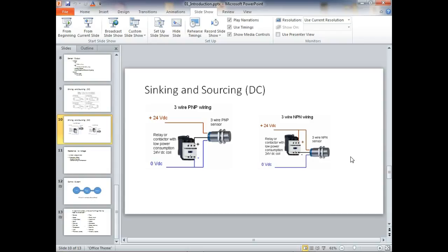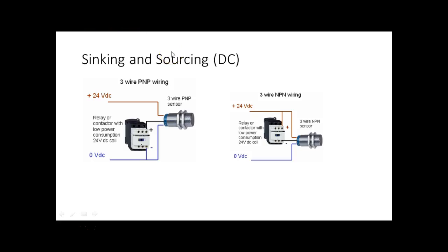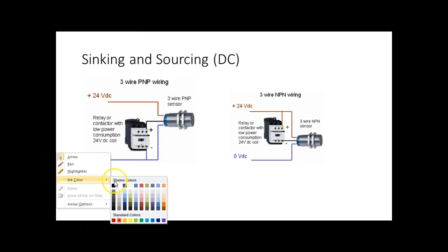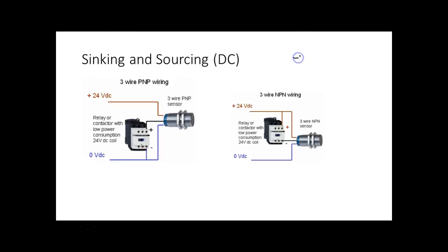You understand single pole double throw? Everybody okay there? The types of switches that we have. Anybody need to go over that? Well, we have different types of switches, and most of y'all are familiar with this one. The number of switches you have, we call it the number of poles. So this would be a single pole, single throw switch. This is what we use for our light switches and everything. Then we come over here, we bring in one switch, and then we give that switch 2 different conditions. This is a single pole, double throw. So some of our sensors are single pole, double throw, and we call them 4-wire sensors.